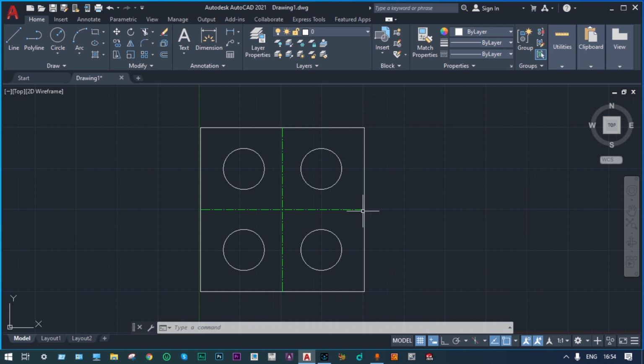Now we have to utilize different things. Suppose you have to make some hidden line in between anywhere else, right? A hidden line, so we have to go back to the hidden layer here. Hidden layer is by red color. Suppose you want to provide one hidden circle in between them. So we have to start with hidden layer. We have already selected. Next one, suppose you have to provide a hidden circle inside these 4 circles. So we have to select the hidden layer. We have already selected the hidden layer. Now starting this circle over here.